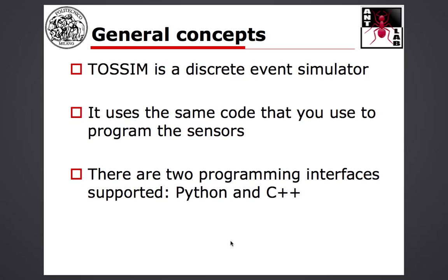Now, the framework in which you debug those applications is generally a small source file. We will see it today, which can be written either in Python or in C++. But this is just how to launch the simulation, meaning how many nodes you want inside the simulation, and so on and so forth. The code that each mote will run is exactly the same TinyOS code that you will then load on the real hardware.